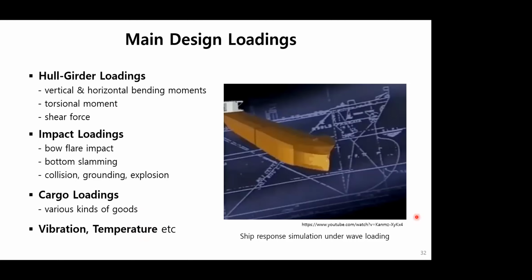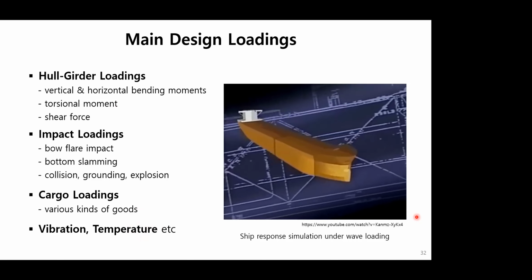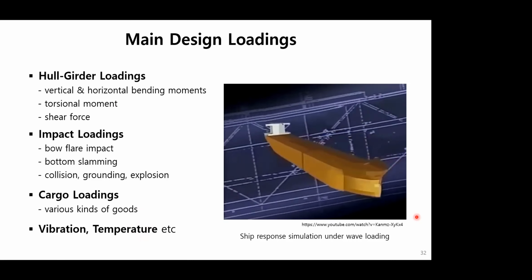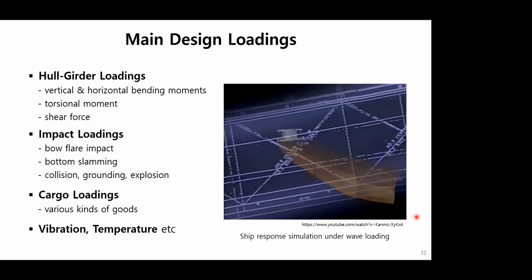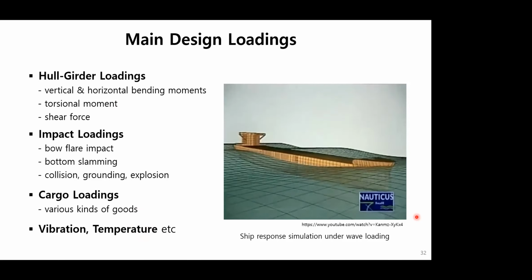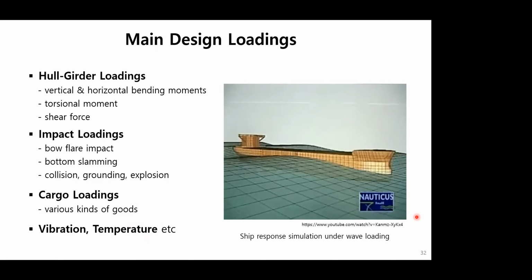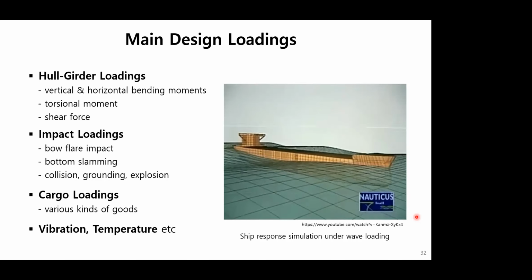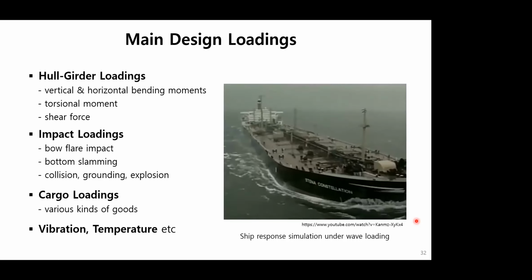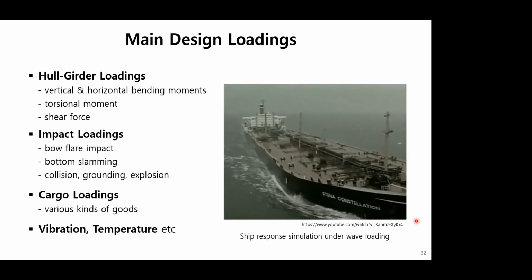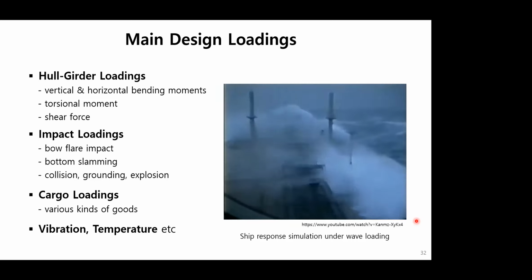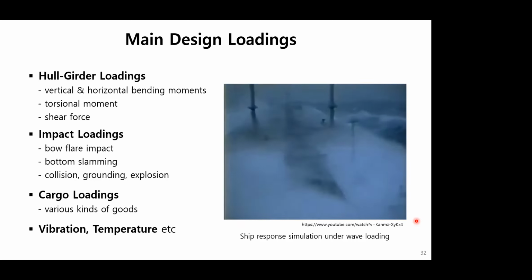Now, here is a good video showing wave loading and ship response. But a simple understanding of the strength and forces acting on a ship's structure is also important. An optimal ship structure has the minimum amount of steel to provide the strength and stiffness necessary to withstand the full range of internal and external forces exerted on it, from sources such as the light ship weight, the weight of cargo, ballast, fuel, etc. And of course the harsh sea, marine environment, the movement of the ship and vibrations.